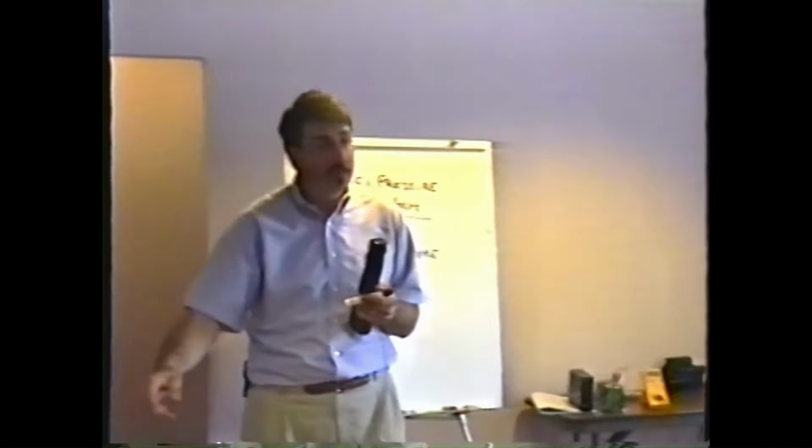That's the source path, isn't it, right? The path from the source to the load, which in this case is my radio. My source is the battery, load is the radio. Well, remember, I need to have a return path for a complete circuit, and the return path is back to ground like this. Can everybody see that by putting a ground symbol here and a ground symbol here, it's electrically exactly the same thing as if I were to draw a wire in between the two?